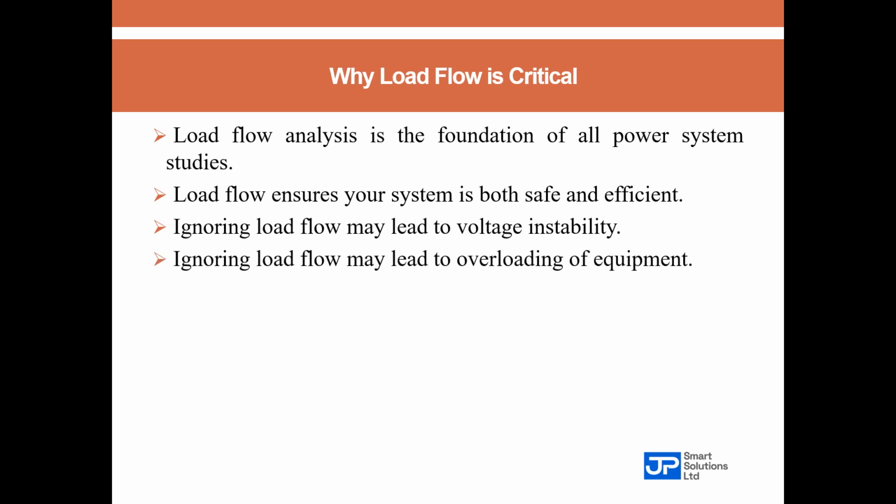Ignoring load flow analysis may lead to overloading of equipment. Overloading of equipment such as your cables and transformers, when they run hot, leads to fire hazards. Just as the first case I explained to you, where their transformer was overloaded. The reason was they ignored load flow analysis. So I'm sure after this you won't make the same mistake.